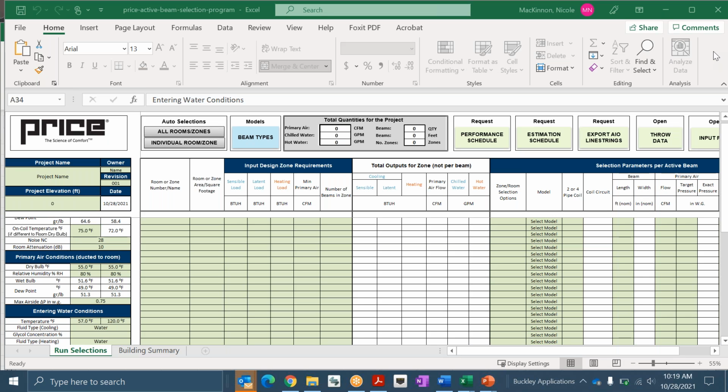Nathan mentioned two other numbers. Don't go below 0.2. And the 0.2 piece becomes a function of our ability to induce air through the nozzle. So going back to the basics here, the velocity as it goes through the nozzle is really the power we need to induce air from the space.